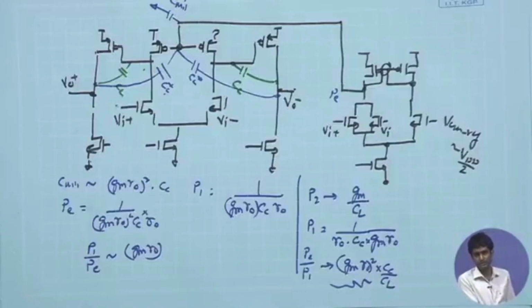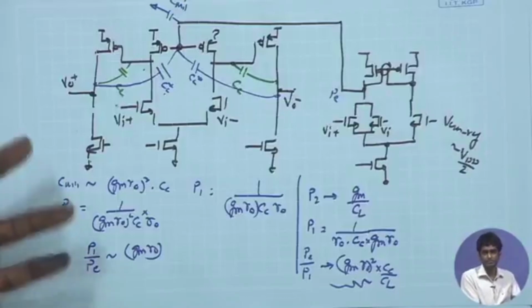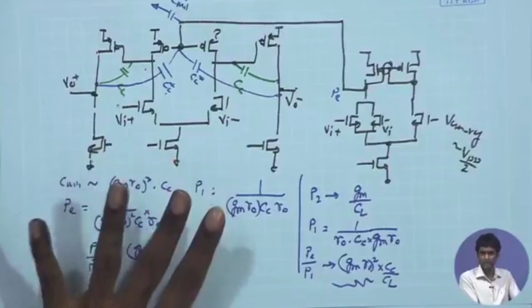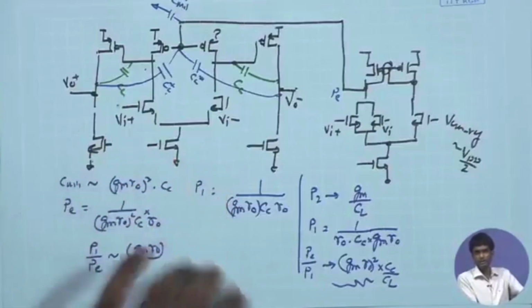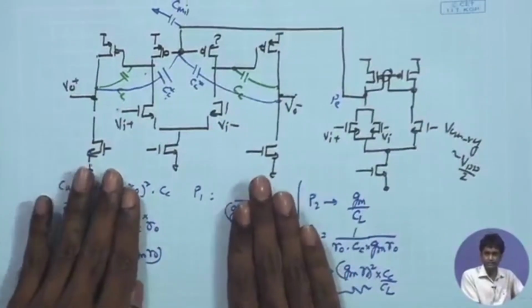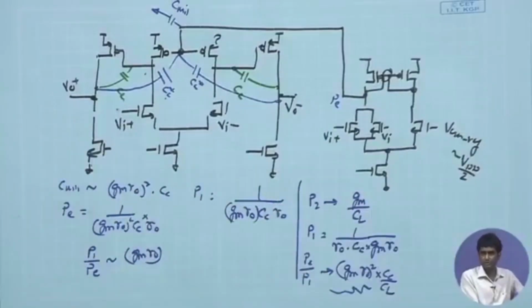Likewise, when we go for switch capacitor circuits or more complicated feedback systems, sigma delta modulators for ADCs and so on, there you have similar cases. You have multiple loops where we need to take care of the stability of each of those loops. So here we are dealing with the front end amplifier only and trying to see the stability considerations in order to make the DC point stable enough, and at the same time make the differential response stable.